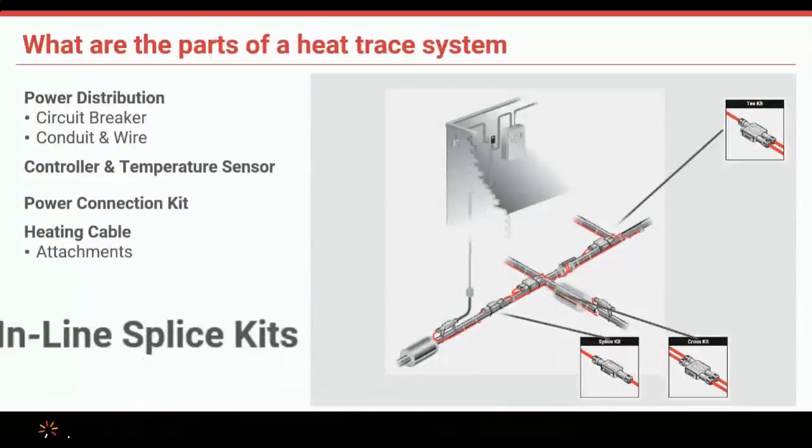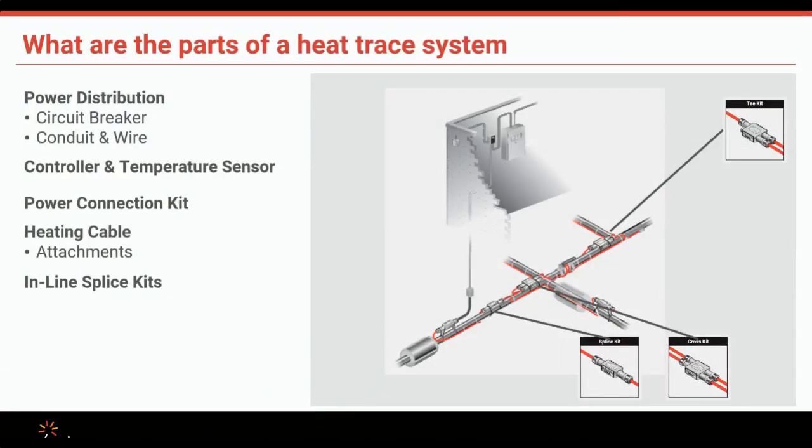Next, we have components. Self-regulating heat trace is a system that is field cuttable, spliceable, and teeable, so we have a number of different options for you in the field. If you have questions about what we have to offer, T connections versus splices versus X's, we have a design guide as well as an online tool that can help along the way, but always feel free to call us and we can work you through that.